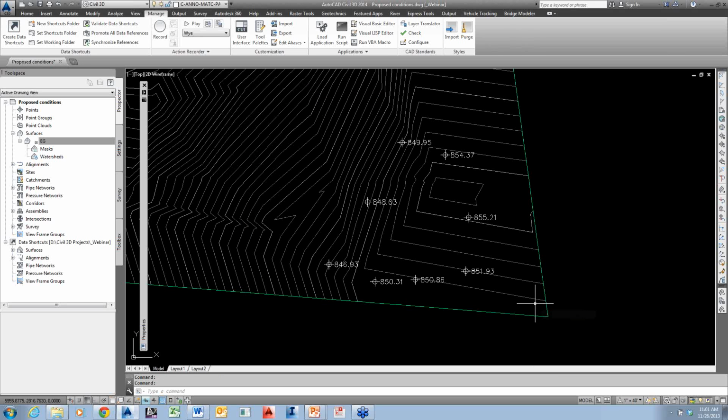And we have one last question, and then we'll sign off here. Can we add a line to a surface with the same X and Y coordinate, but in a different height? In the original surface, absolutely. I just add that as a break line to the original surface. In the data reference surface, no, because I can't edit the data to it. Yeah, it all comes down to that data.